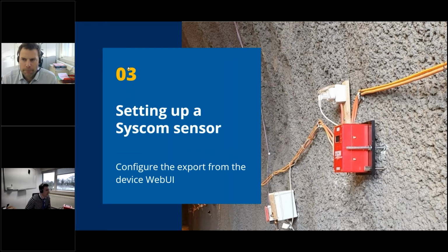After that, there is another question. It has been mentioned that the MR3003C is a data logger with a 3-axial sensor, but is it possible to connect some additional vibration sensor? No, not on this one. It's only 3 channels. We have another device that is specifically designed for blast applications where sometimes you need air pressure. In this case, you will have a 4th channel, but it is limited by 3 channels. The idea behind that is to have a distributed network, meaning each point in your network will be standalone.